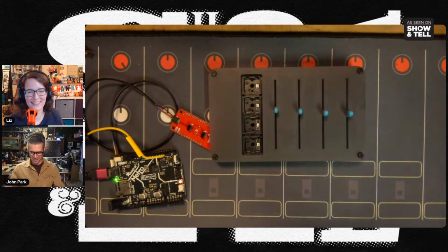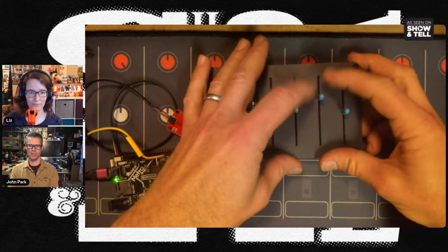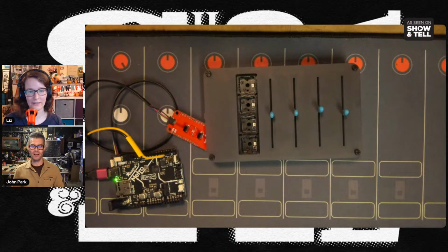So I'm going to be taking 16 of our 75 millimeter slide pots. They have a 60 millimeter throw. I'm building a PCB for it, and we're going to be able to do some really cool things even beyond this project with it. I think it'll be kind of a neat platform. We have a couple of 8-bit ADCs that'll work well to allow us to read these faders and do cool stuff with them. So that's what I'm working on.